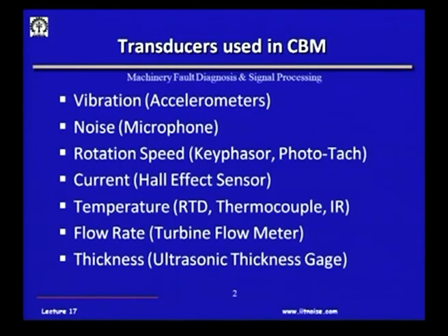But the turbine flow meter is another device which could be very easily put online on a pipeline, and all you get is the speed at which the fluid is flowing through it. Once you know the area of the pipeline, if you multiply that, you will get the flow rate instantaneously. So, when the processes are very dynamic, when the flow rates are changing because of the operations on the plant, particularly in large oil refineries and chemical plants, that is where we use turbine flow meters.